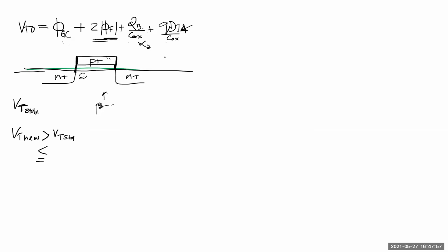So when we calculate QB and we take the acceptor ion, because you remember this was N plus, right? And we always took the acceptor ion to calculate these two. So that's dependent on the substrate because you're talking about the surface potential of the P and the QB of the P minus. That we are not touching, right? You got it right. So actually none of these should change.